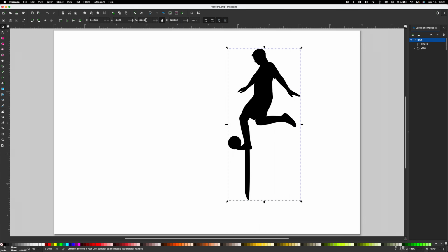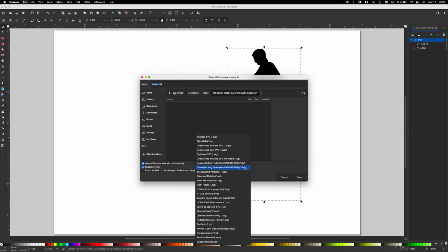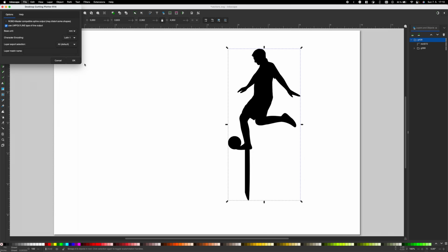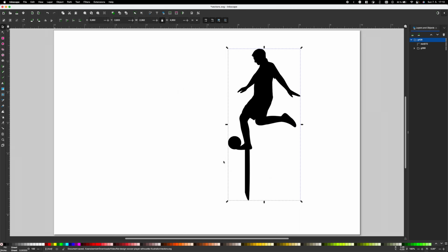If we are happy with the result, we can save a copy of the image in the DXF format. Unfortunately, this is probably the only format we are able to load into OnShape for our needs. If we get an error message during the export, it probably means that the image will have incorrect dimensions. There is a simple solution to this.